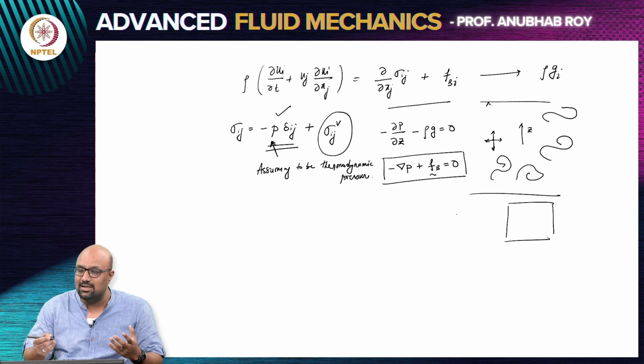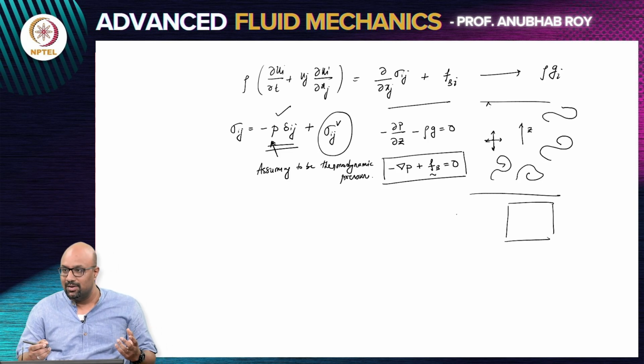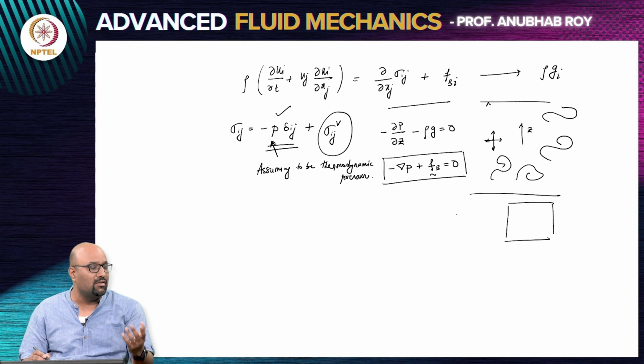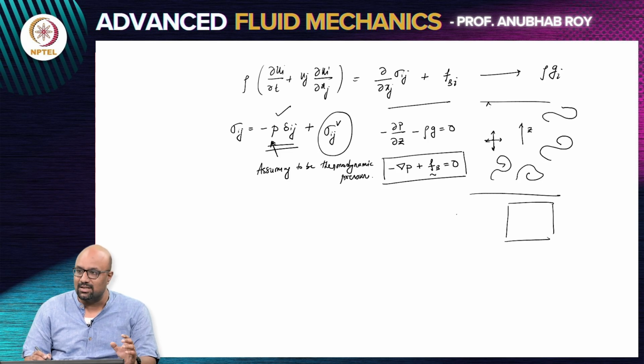So, that is the concept of relaxation when the fluid is made up of something other than what you are thinking of as just billiard balls. In which case the relaxation time scale can start to approach fairly large values, large with respect to what we understand for fluids like water like systems. If the relaxation time scale starts going towards a few milliseconds or even higher, then the consideration of thinking of the system being in thermodynamic equilibrium gets a bit dodgy. But we are going to proceed with only thinking of fluids which are more conventional in terms of how we are designing it. So, fluids which are water like systems.